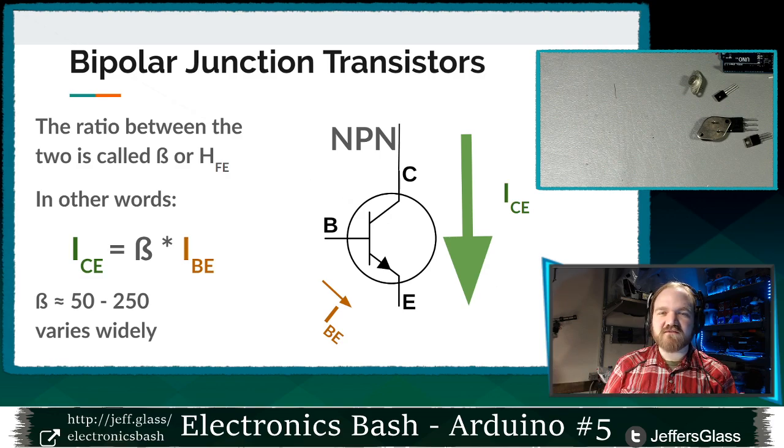It has to do with manufacturing tolerances of the materials that these transistors are made of, and the tolerances generally are not very good, to the point that it's actually quite a bit of work for some specialty circuits where you need to have two identical transistors. It's really hard to get them to match each other, especially because this parameter, this beta, as you might have guessed, changes with temperature.